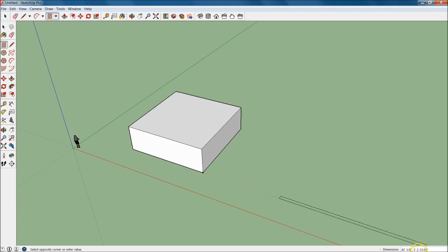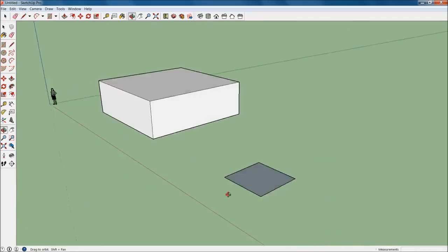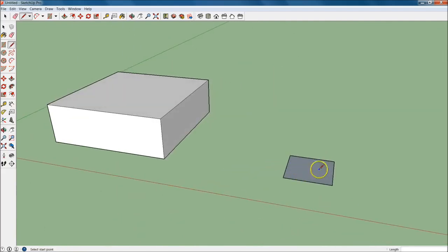And you'll see that these dimensions, how they're formatted, are a little bit different. Let's go ahead and pull this out. And we're going to make a 10 by 10 shed. How this is formatted is, it'll take your X, and then it'll take your Y dimension. You'll see that there's that comma right there in between the two. So what we're going to write is 10 feet, comma, 10 feet, and hit enter. And you'll see that it's 10 by 10. Double check it. 10 by 10.